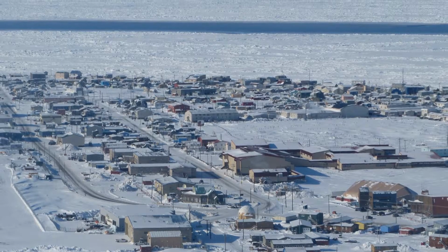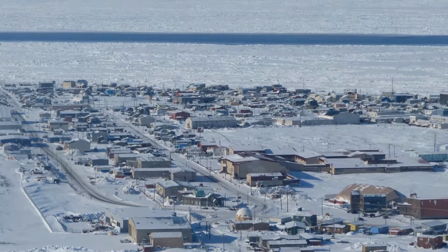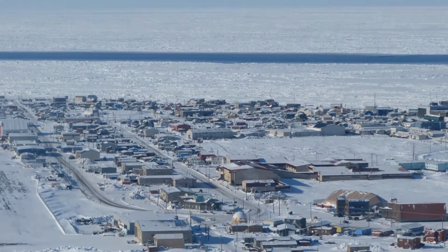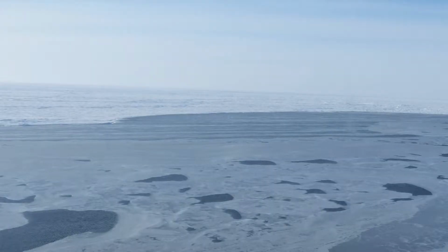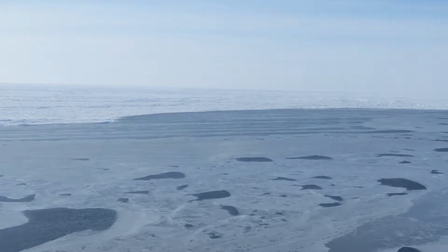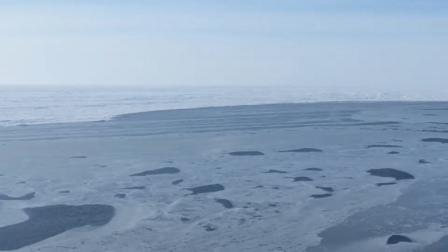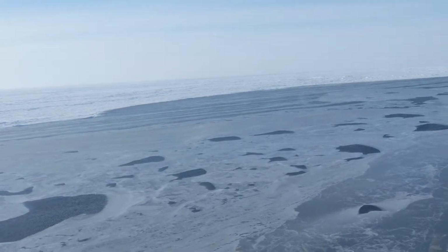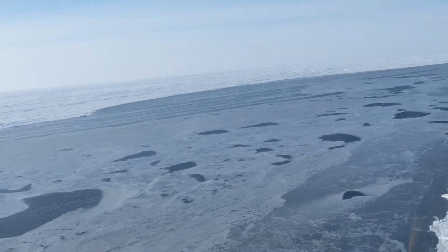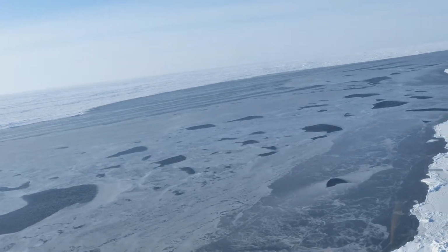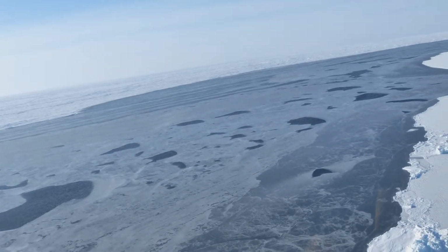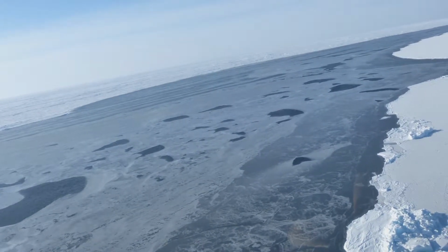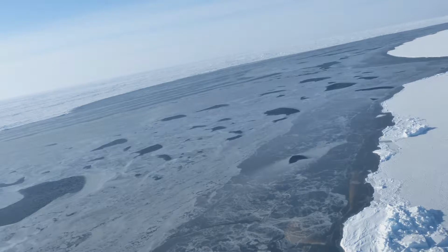If you go back 10 years ago and you'd have asked, okay, how thick is the really old ice that passes by Barrow, you might have said, well, 4 or 5 meters thick. And we just don't see anything like that anymore. The really thick ice is 2.5 to 3 meters thick. It is the thickest level ice that we find in the region that we associate with the old multi-year ice. We've been looking for changes over time, but we've also just been trying to better characterize the ice and understand these extreme ice thicknesses and the risks they pose for shipping and engineered structures in the offshore region.